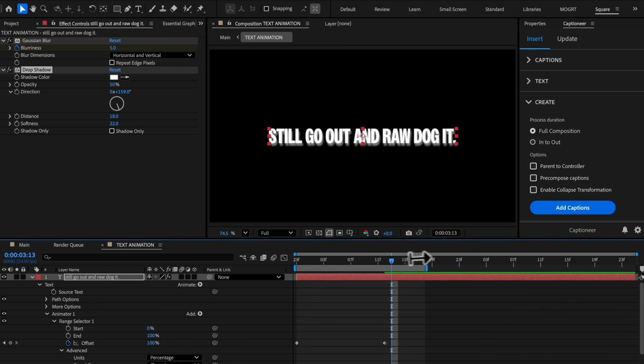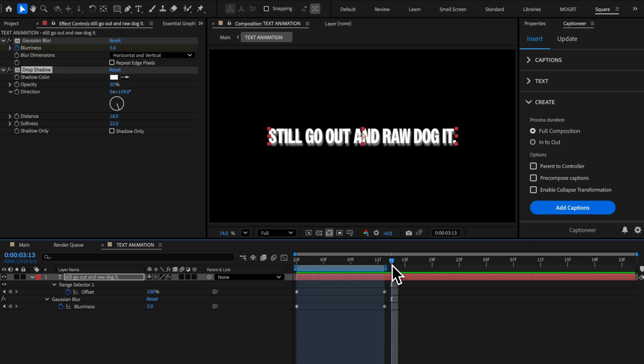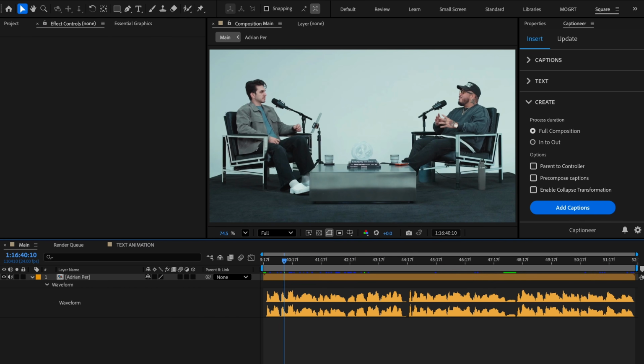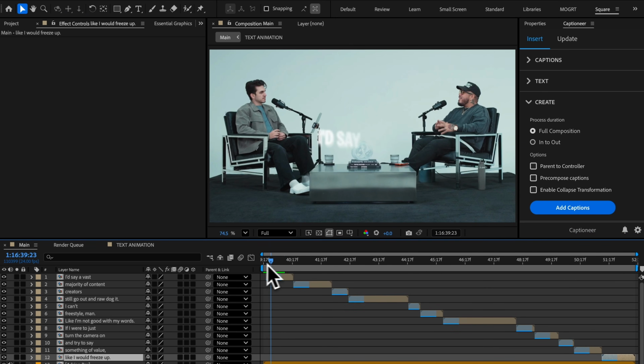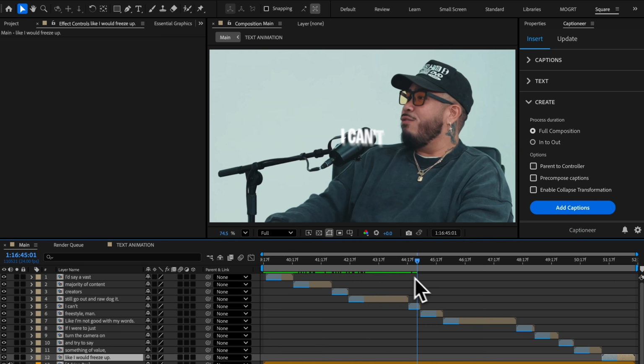You can also add responsive design time protected regions to your precomp. I'll set my work area to the region I want to protect, and right-click, Create Protected Region. This blue section will protect the keyframes inside it, so everything outside will stretch and everything inside won't stretch. Then we can re-add the captions. Now animations stretch perfectly to fit the duration of every caption.